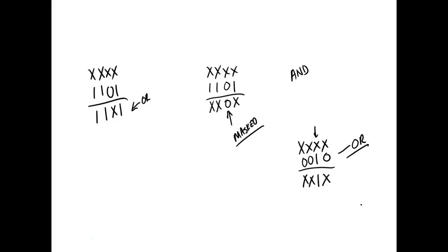So I have a PLC that only has 10 inputs. I'm trying to see if a bit is set or cleared. But I'm going to bring in a 16-bit word. So even if I only have 10 inputs, when I read these registers or load that input port in, I'm going to get a 16-bit word. You understand? So what if we wanted those unused bits to always be 1 for some reason? Well, we could OR it, right?